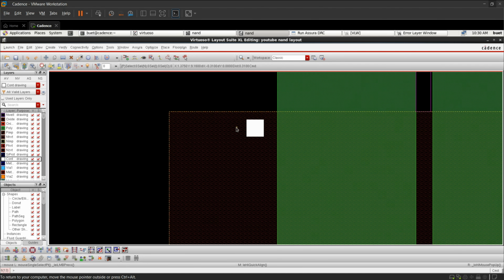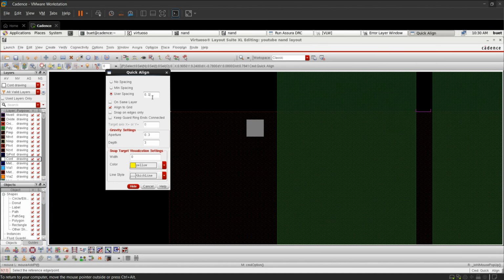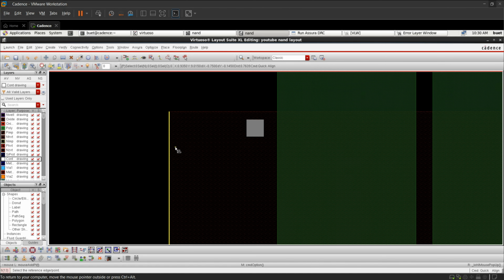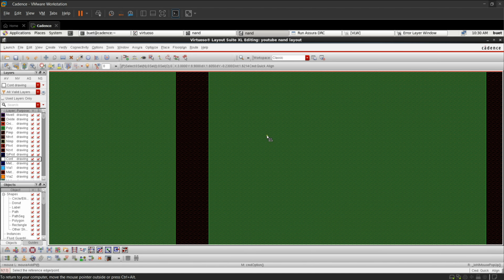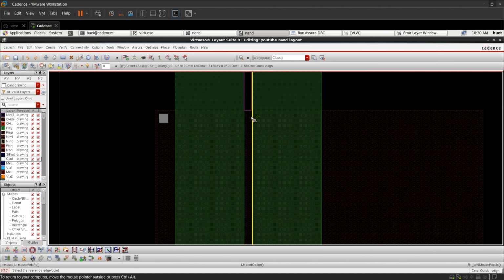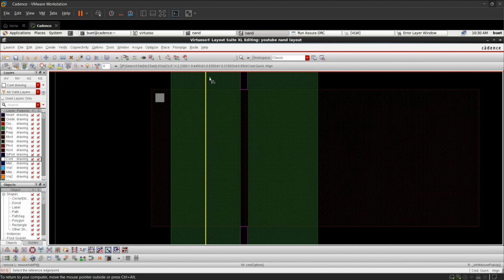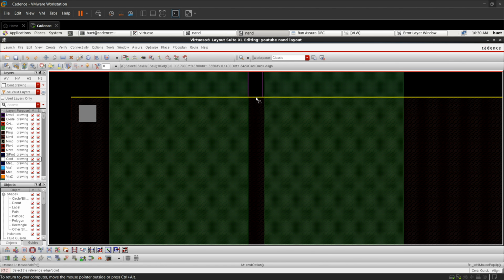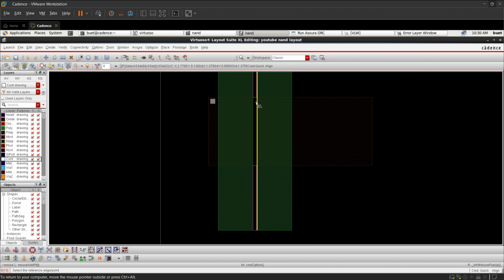This spacing should be 0.06. Again, make it 0.06. Select this edge with respect to this. Now we have got it, but we have done one blunder here. This is the terminal we are going to take as common, so the contacts must be placed in this region also.